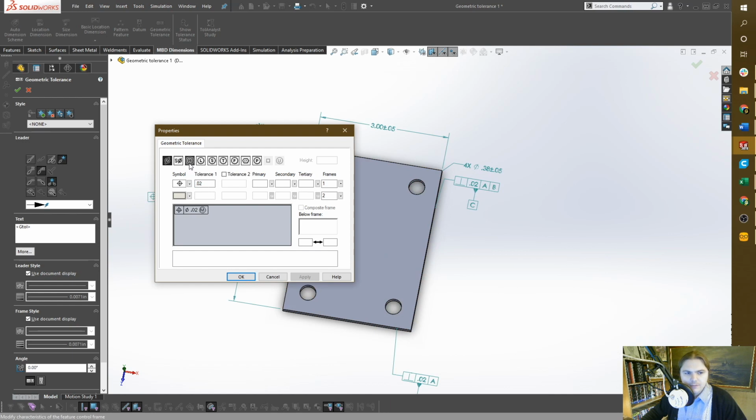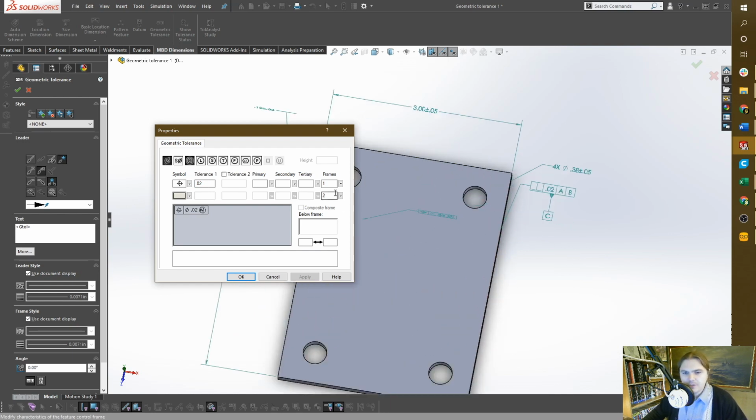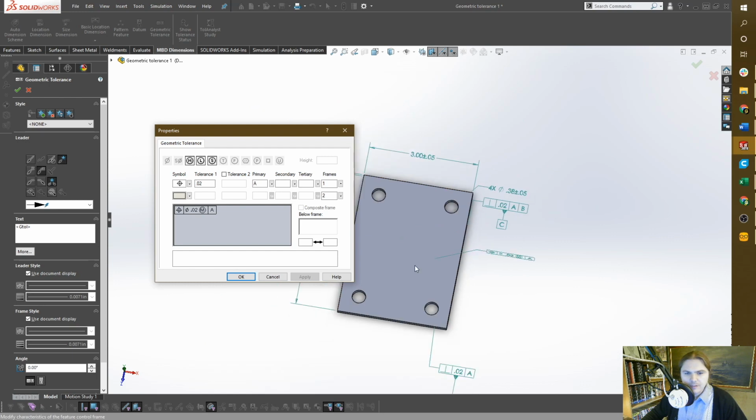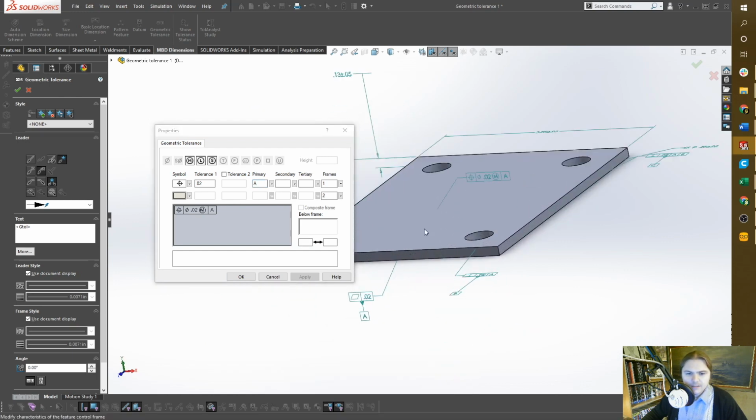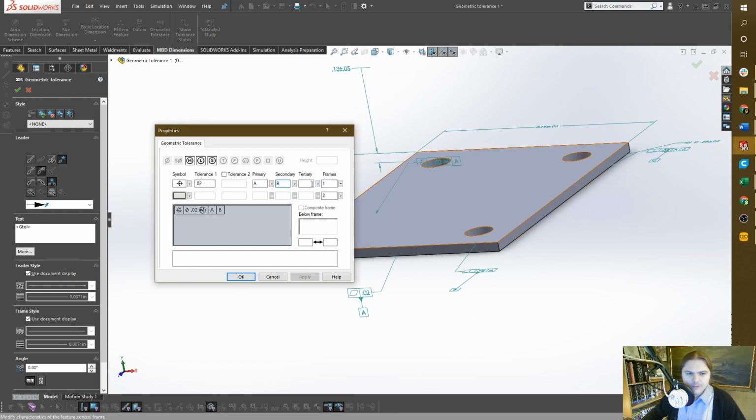And I also want to use maximum material condition, so a part like this could use a functional gauge to check to see if it would function. And then I want this to be positioned to datum A, which actually makes the axis of the hole perpendicular to datum A. And then from there, we'll position from datum B and datum C.